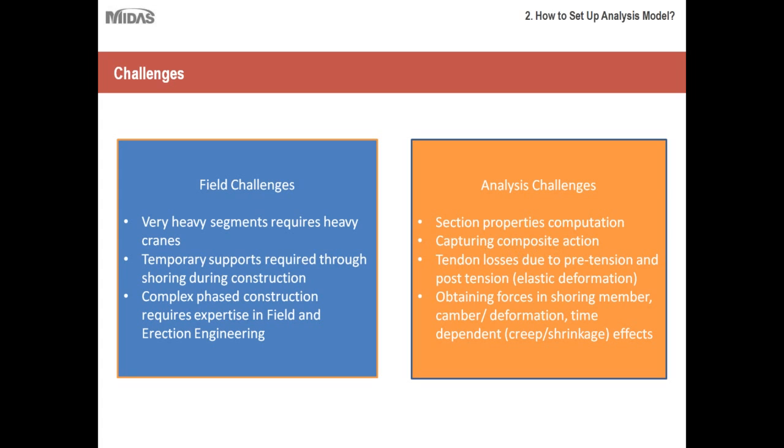Again, this one section is constructed in 3 different steps, and there will be a time where the girder will be by itself, then there will be the girder and the lid on top, so that will behave as one section, and then after some time there will be a third part added to this section. So you have to capture the behavior of the entire cross section in different stages.